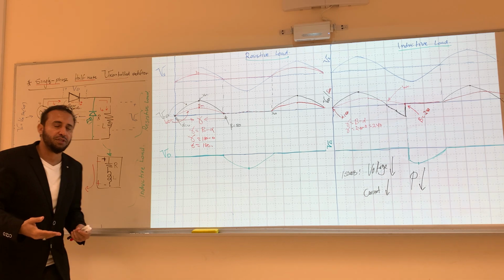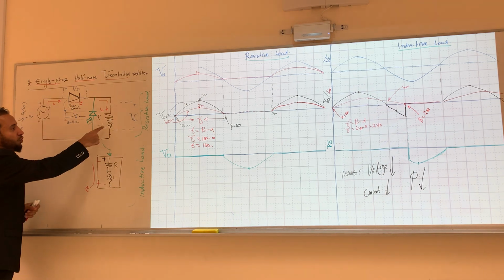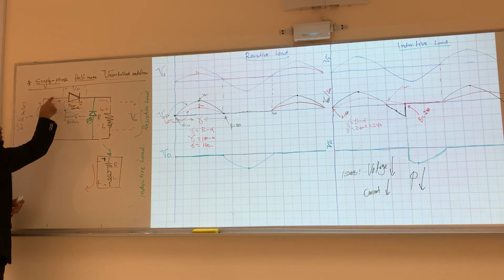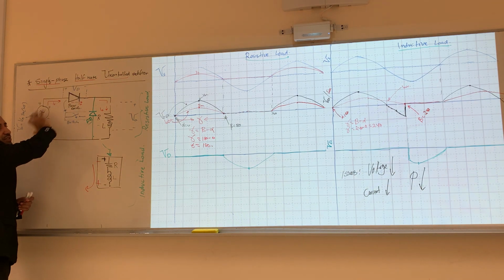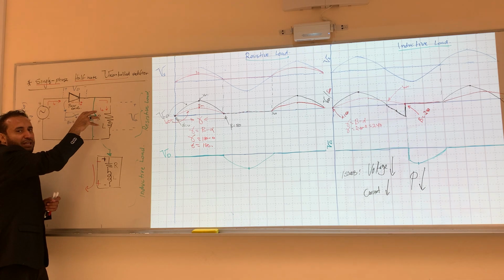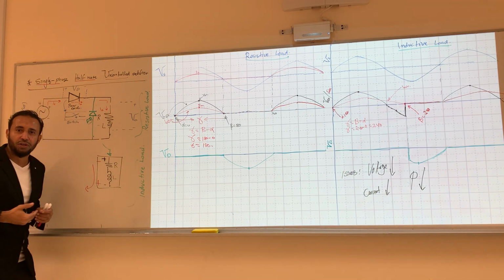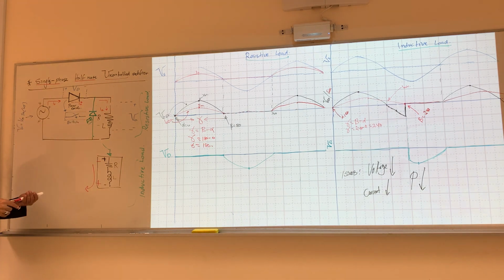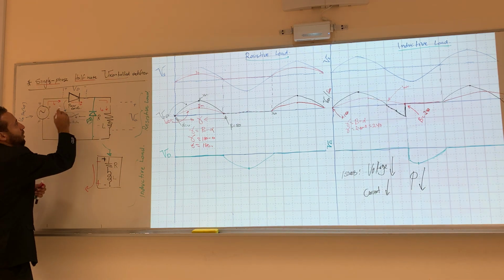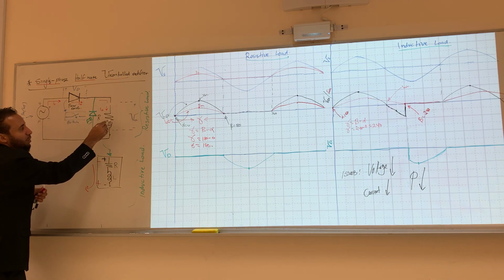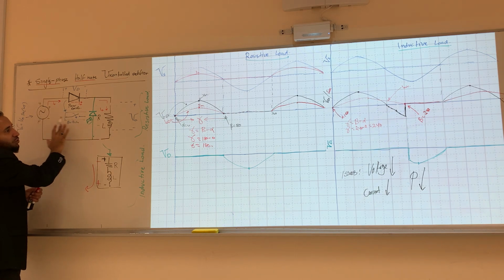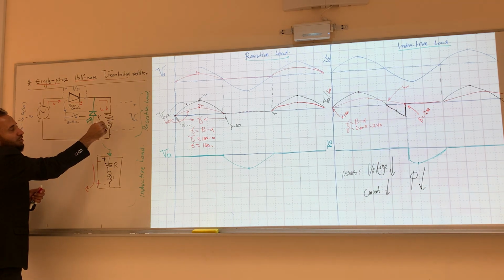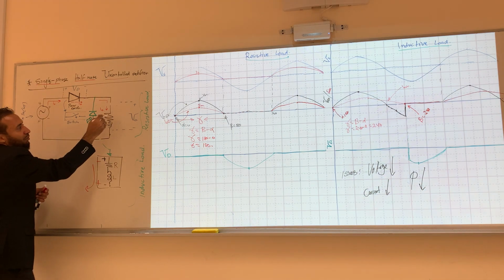It has to discharge. Before, it used to discharge through the power supply, through the power diode, and there's a resistance here. But since we put the freewheeling diode here, we make a short circuit, so it will not flow through there. During the negative process, when this one wants to release, the polarity will flip.